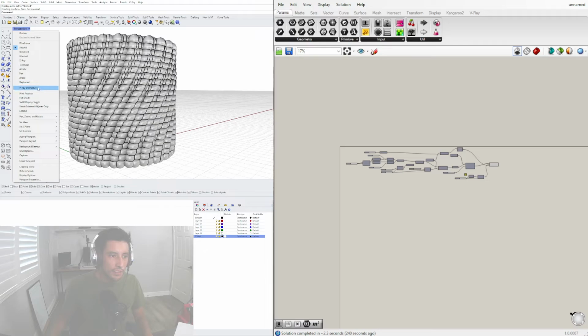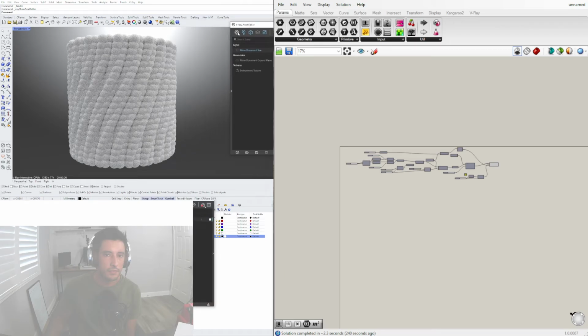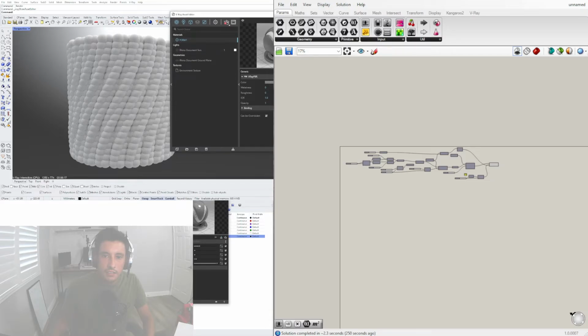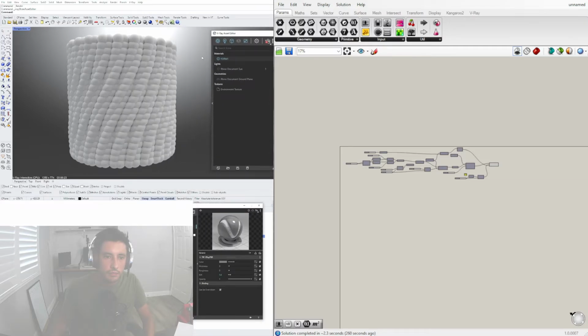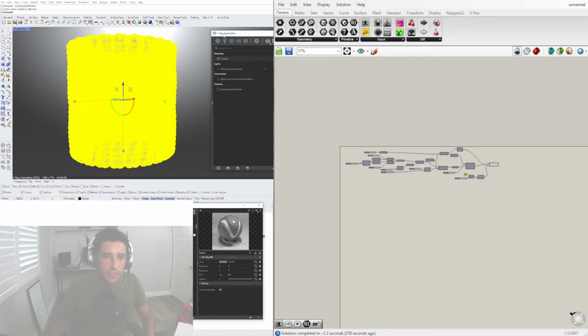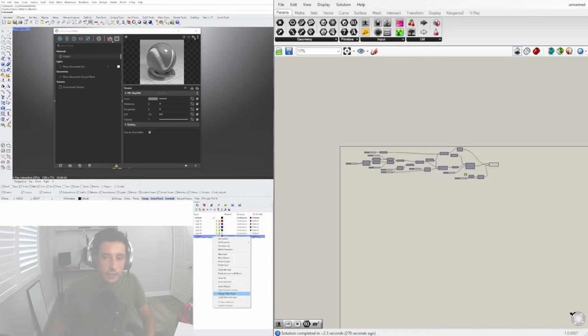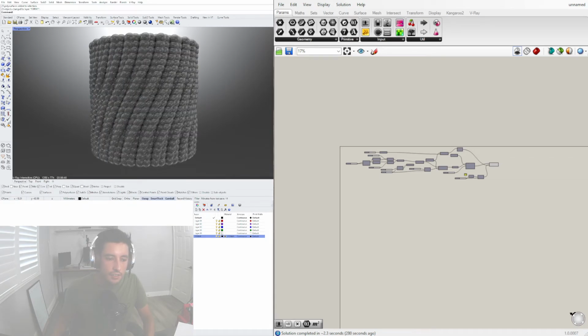And if we go to V-Ray Interactive, let's apply a V-Ray material to this. So I'll go to PBR material, I'll call this form 1, and let's see what it looks like when we apply a generic material to our form. I may have done it in a different layer, so I'll have to select this. I think I had the default layer selected when I did the bake, so I'll just change object layer to this one. And as you can see, looks pretty cool.